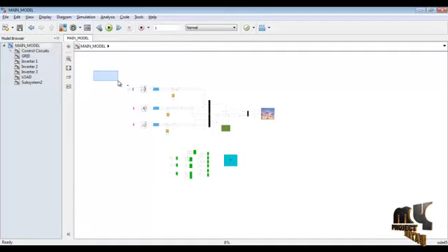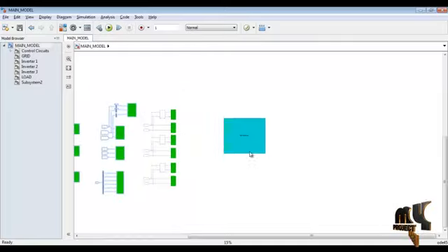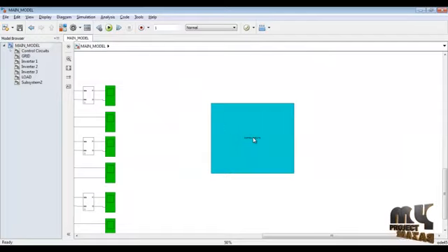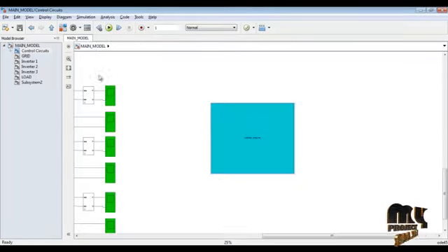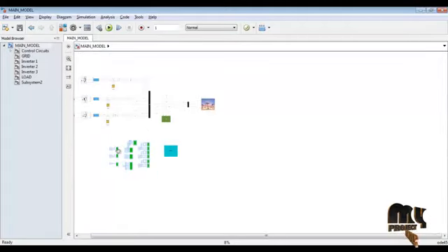Next we can see the block diagram of the product. This is our circuit diagram. This is our DC source, and these pink color marks are the DC source. This is our bridge rectifier, and these are our line control parameters, like RLC. This is a common AC bus, this is a load, and this is a grid. Everything is connected, and the corresponding scopes are connected through From and Goto functions. These are scope blocks, and this is our control circuit. This is our synchronization block, and everything is connected to the subsystem of the blocks, and these are control pulses, and the corresponding scopes are connected through From functions.